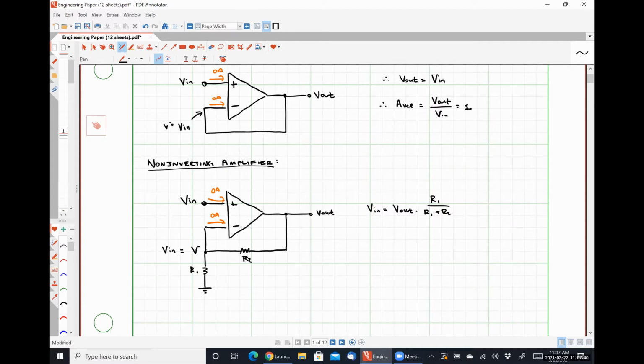So what I am suggesting is that I have some fixed output voltage that is dropped over resistor R2 and resistor R1, and the output voltage sees those two resistances in series because I know that none of the current flowing through those resistors can branch off and flow into my input terminal. Using voltage division, where I have a known voltage drop over these two, I can find the voltage at the node in the middle, and I can rearrange this, and I will find